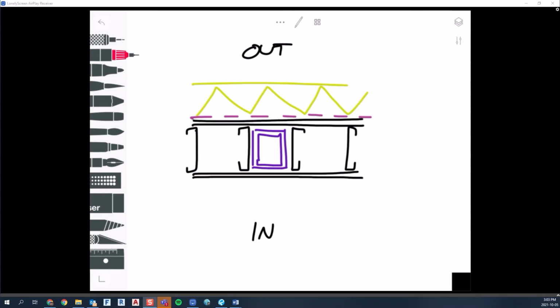So what you have to look for in that scenario, of course, is the size of your column. So what's the size of that? And what's the size of the stud that you're using? So the most common stud size that would be used in Calgary is a 152 stud in the exterior walls. So why is it 152 and not 92 mil?